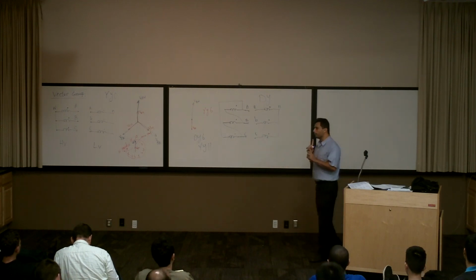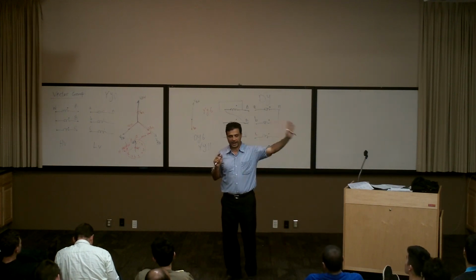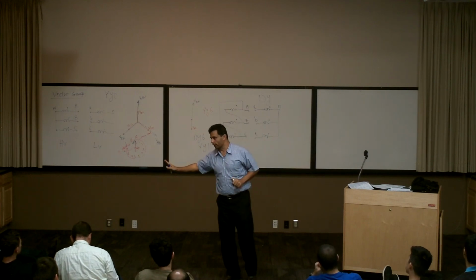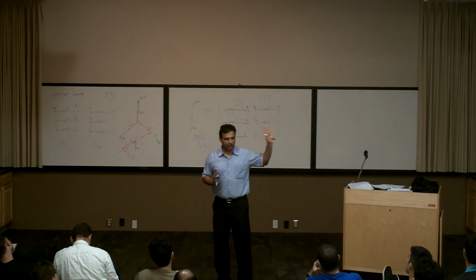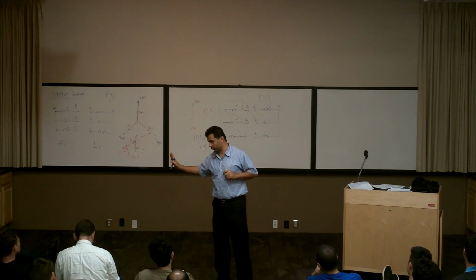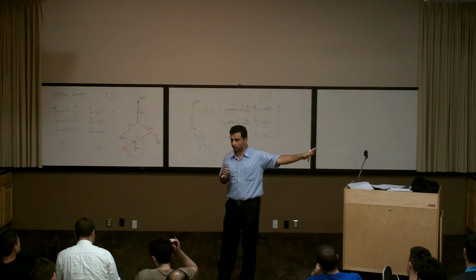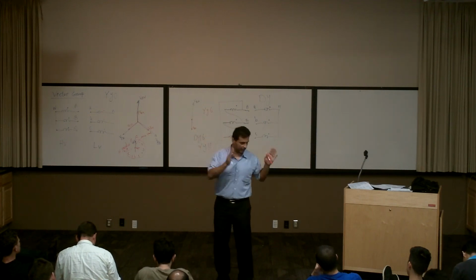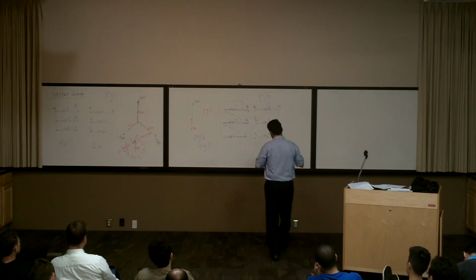I said you should be careful about what you are doing. You should compare phase A of the high side with phase A of the low side. Or, if it's easier, you can compare line AB from the high side with line AB of the low side. You should keep it identical. You cannot select phase A from the low side and the line from the high side. It should be either phase-phase or line. The phase-phase is easier, but let's start with this one.